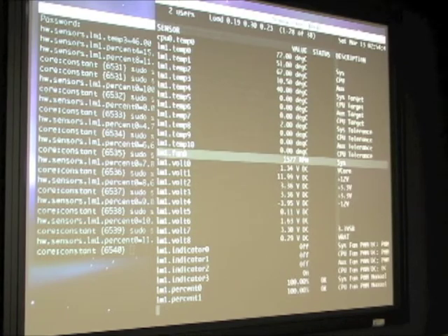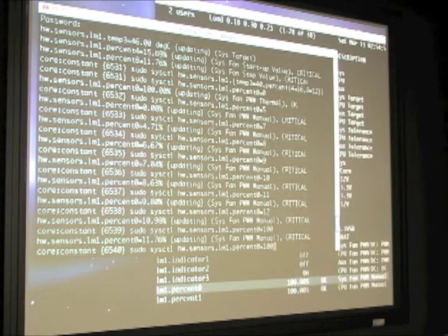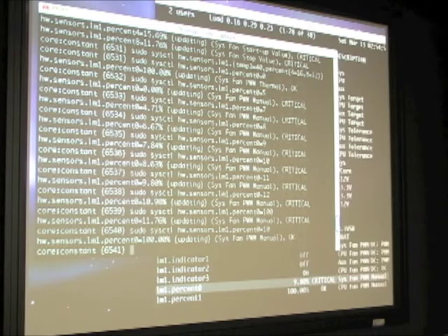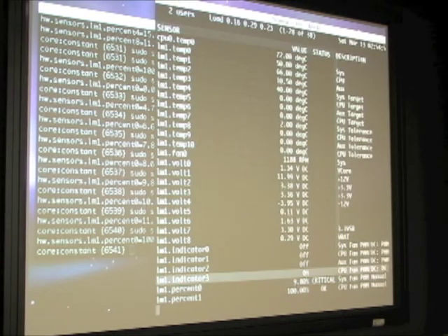So we set it to 100 and you're back. But then if we set it to 10 after that, then it is going to work. And the reason is that for the fan to start, we need to supply higher voltage, and for the fan to continue running, lower.